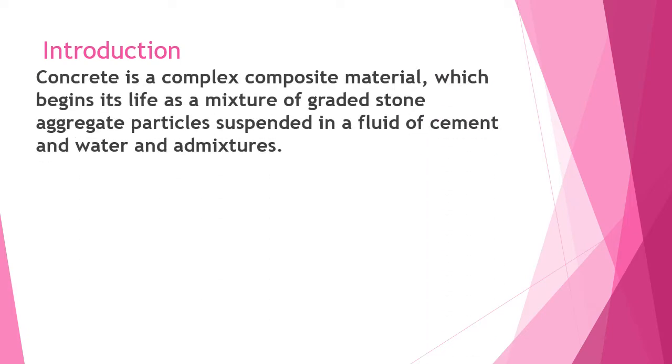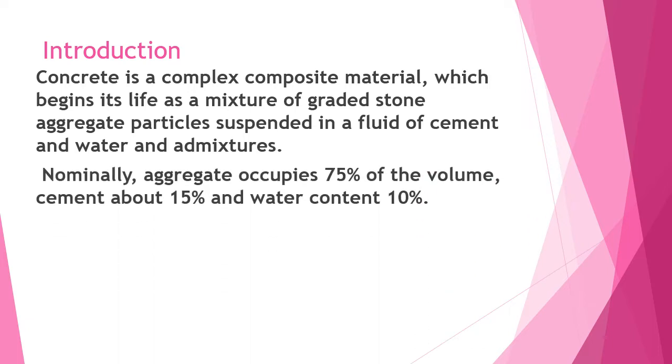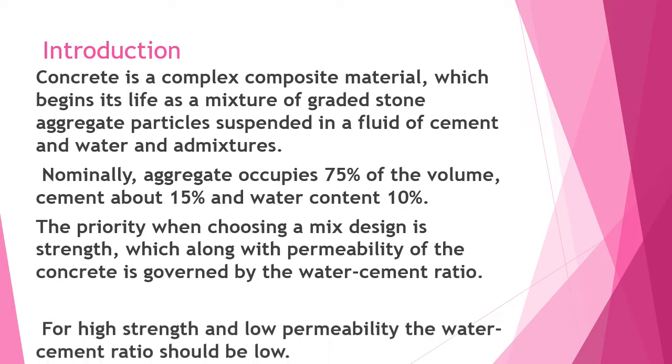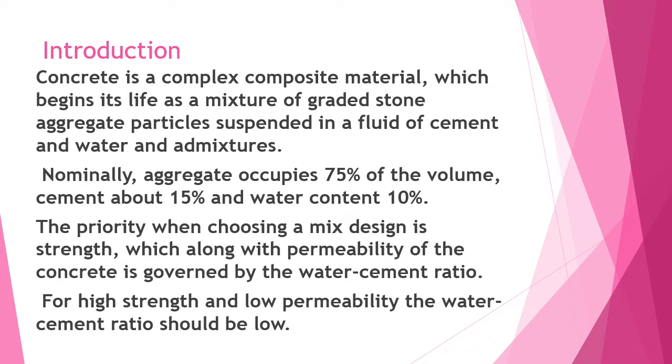Introduction. Concrete is a complex material which begins its life as a mixture of graded stone aggregate particles suspended in a fluid of cement, water and admixtures. Normally, aggregates occupy 75%, cement about 15%, and water content 10%. The priority when choosing a mix design is strength, which, along with the permeability of the concrete, is governed by the water-cement ratio. For high strength and low permeability, the water-cement ratio should be low.